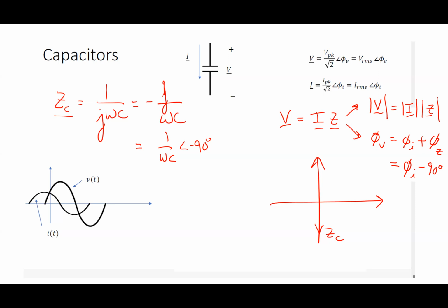Well, it seems that way, sort of, I guess. The way I think of it is, if I look at one individual cycle, I have one cycle in one period. Whichever one comes to its peak first in time, meaning more to the left, is the one that leads. Whichever one comes to a peak second lags. So if this is I and this is V, who leads? I leads, okay? And that's how that manifests here.